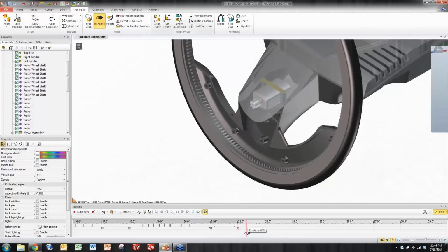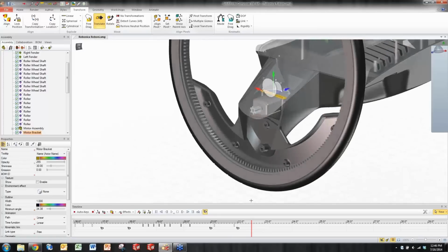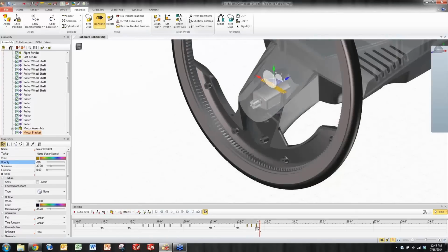I'm going to use the flashing key on this bracket. We're going to make this disappear. So I basically come to where I want it, highlight the opacity key, and we're going to set up the effect of a hotspot. I'm going to record these two keys to make it flash more than once. And then after that portion of the animation, you'll see it flash even when it's selected. You can see the property moving within the property manager.